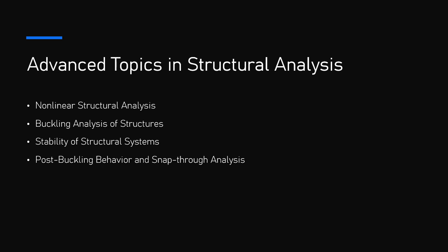P-delta effects. These effects occur in structures under vertical loads, such as gravity, where large lateral displacements cause an additional moment due to the offset between the applied load and the deformed geometry. This is critical for tall buildings and structures with slender shapes. Instabilities. Geometric nonlinearities also play a role in buckling, snapping, or instability phenomena, where small changes in loading can cause a sudden and dramatic change in structure behavior.